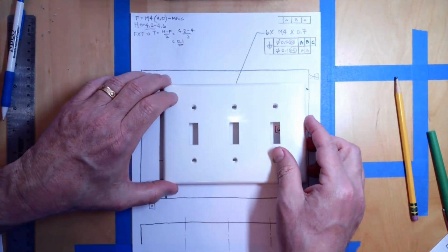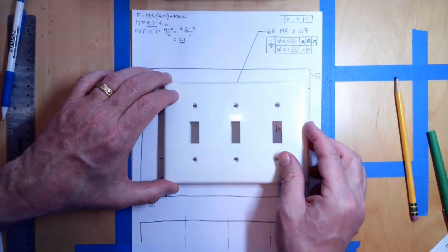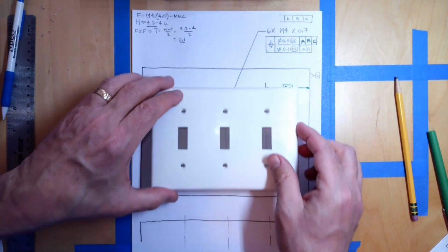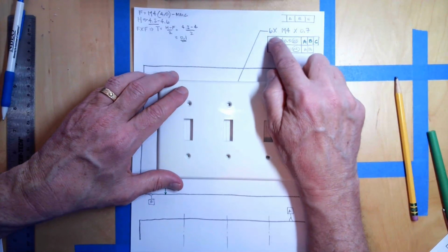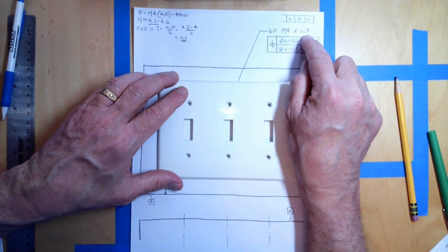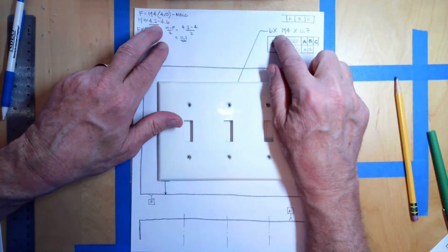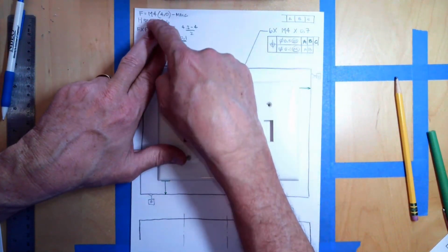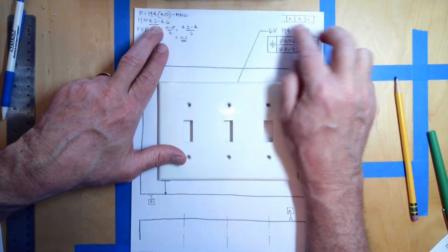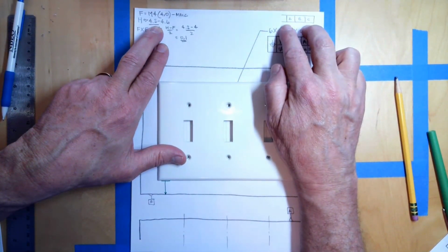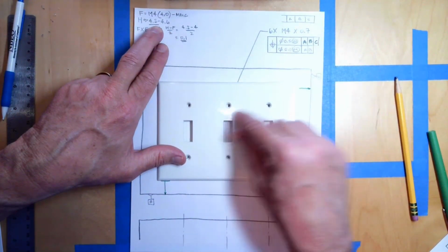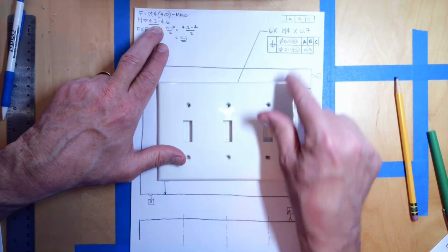Now, if we went on to design the cover plate, what would change between this drawing and the cover plate drawing? Well, the 6 times M4 by 0.7 we would replace with the hole dimension, 4.2 to 4.6. So this thread note will go away, and it'll be 6 times 4.2 to 4.6 and something for the countersink.